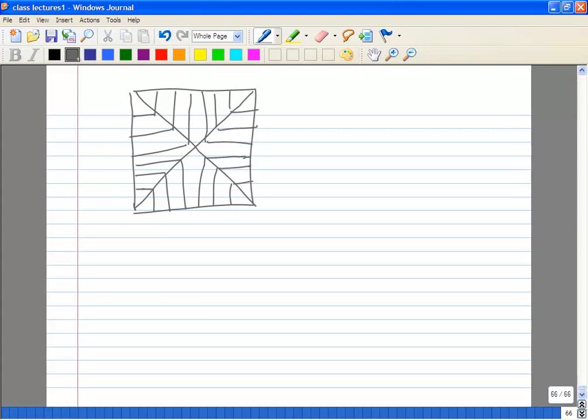Okay? So each one of these is actually a metal or poly strip, okay? And each one of these lines is a slot. So it's basically an empty space between adjacent metal strips, right? What will happen? Obviously there cannot be any eddy current flow, because now you have slotted it, you have created an open circuit.